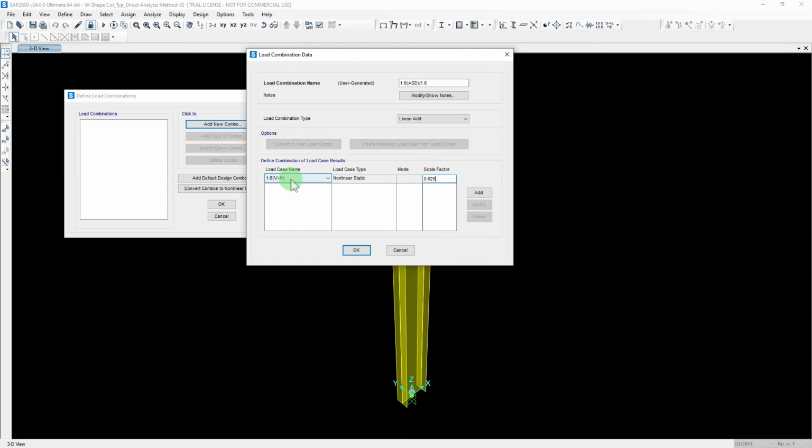So it's a manual implementation that's required by the engineer in SAP 2000. As far as I know, there is no automatic way of doing this. If you know of something, leave a comment in the comment section below, and we'll discuss it. But in my years of experience and talking to SAP and their technical support, this stuff has to be done manually. I believe you can find this information in the help of SAP 2000.